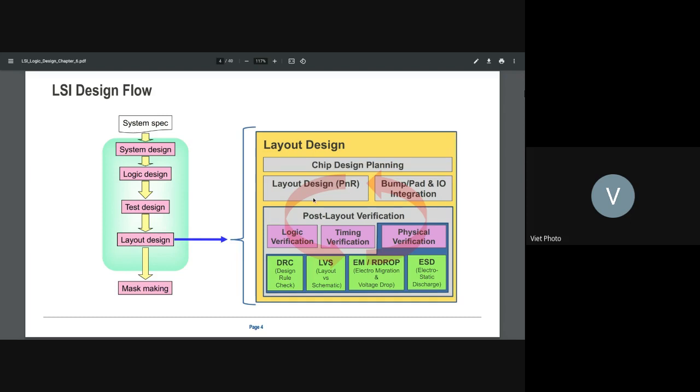But the CTS is very crucial because the CTS is the reference of everything, right? It's the clock, so it's the reference. If the reference is bogus, nothing works. If the reference works, meaning the CTS is good, even if placement is not good and route is not good, it still works somehow. But if the CTS screws up, then nothing works, which we'll talk about later.